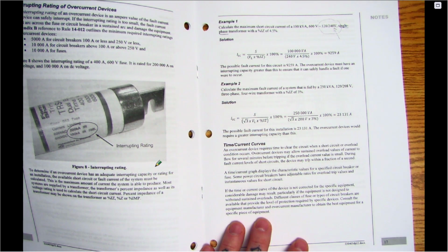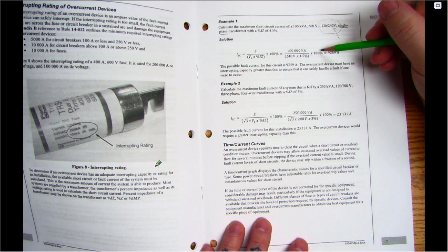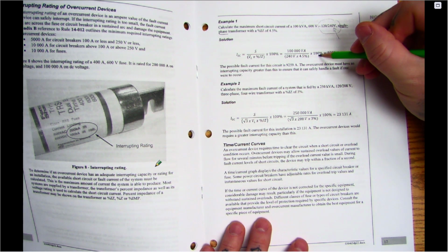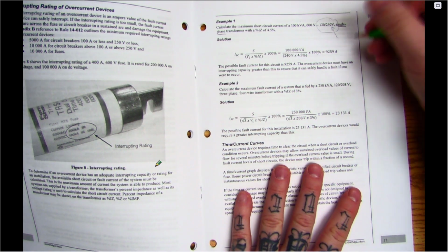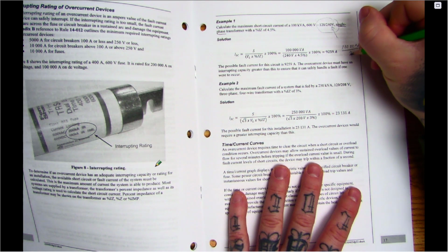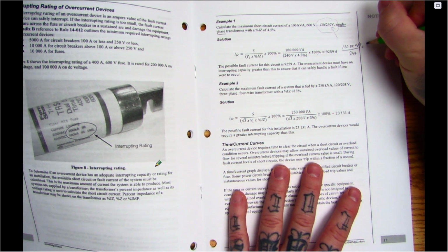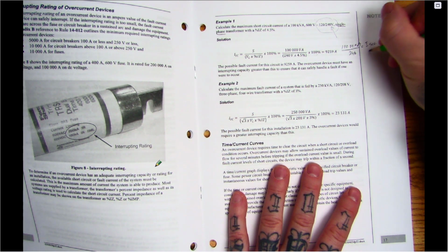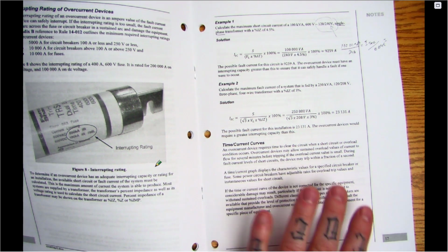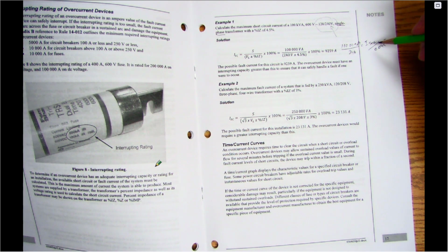Okay, so you'd put that in at 0.045, or maybe not because you multiply by 100. Sorry, I do this differently. I take 100 kVA, divide by 240, then I get the I of my secondary, then I take that divided by my 0.045, and I get the same answer. That's just how I did it in 3rd year, so that's how I still do it. It's going to give you the maximum short circuit current.